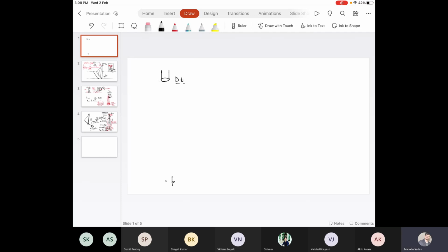But due to some limitations of the internal instrument and electronics, as well as diffraction in the medium, the energy hitting around point P covers a specific area. We'll call this the footprint, with diameter of laser footprint df, and df is always greater than dt